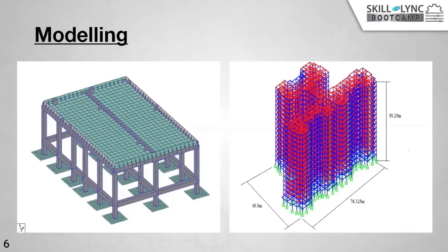If you model that slab somewhere 1 meter above the beam location, you will not be able to transfer the slab loads into the beam, but in the field, that is not what is actually going to happen. So whatever we're going to construct in the field, it should be properly modeled in the software, so that you will get a realistic output and proper results.